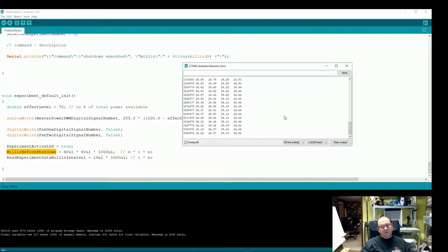You need to store data in the EEPROM, and that's very limited. I think it's like 1 kilo. And even if you go to the Arduino Mega, you get 4 kilos, but yeah, that would be quite okay. But I'm actually thinking I'll send this data to the computer, and the computer will just basically capture all the incoming data from the experiment, and even possibly execute several experiments one after another. Yep, so that will be the next phase of the initiative.